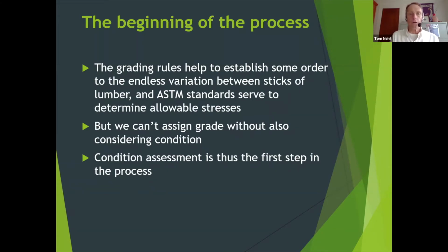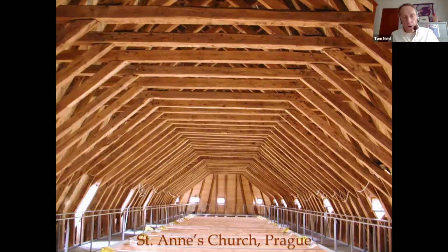So that's good, but before we get to that grade and use it to establish our allowable stresses, it's important to remember we need to know the condition of the wood as well in an existing building. So condition assessment is going to be our first step. I'm borrowing some slides from my colleague, Ron, and this first one is of a 900-year-old church in Prague.